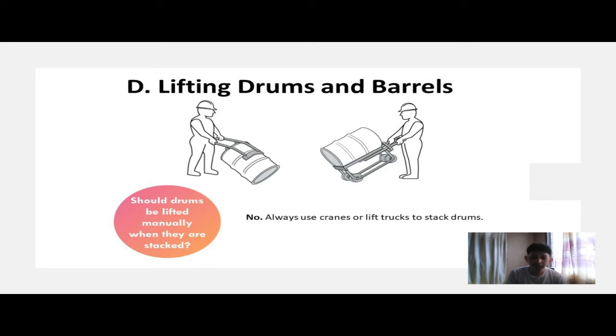As what I have said earlier, lifting of drums or barrels can be dangerous. So, for that reason, you can use some drum tilting lever for upending filled drums that reduces the effort required to move such drums manually. You can also tilt drums by using a tilting drum stand to move emptied barrels and drums.